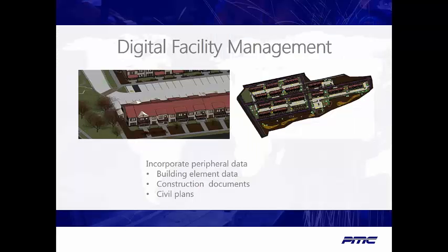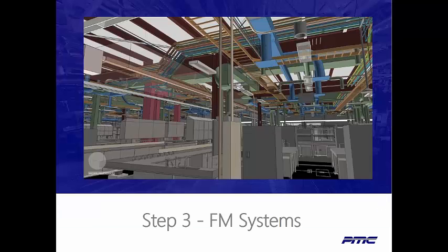Once the 3D model is completed by the architect, element data can be incorporated. A virtual mock-up of the materials or takeoff sheets can be created, giving an accurate costing of the project. Additionally, accurately placing the model in the civil site plans before construction in a digital model can identify incorrect or missing parts of the model. If proper modeling guidelines are followed when creating the BIM, the geometry and data will easily import into most digital facility management systems.